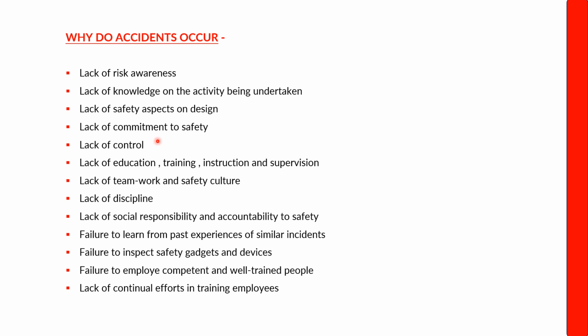Because the tag should be there, it should not be torn, the d-rings and turnbuckles should be in good condition, the stitching should be good, and there should not be any cut in the harness or lanyard. Also, before using any ladder, you have to do a visual inspection.